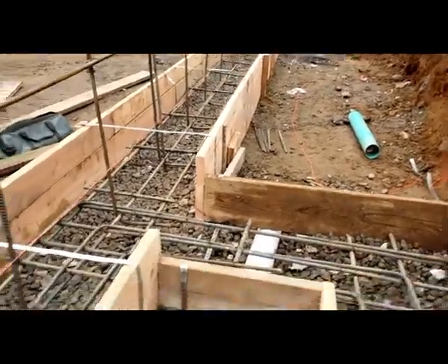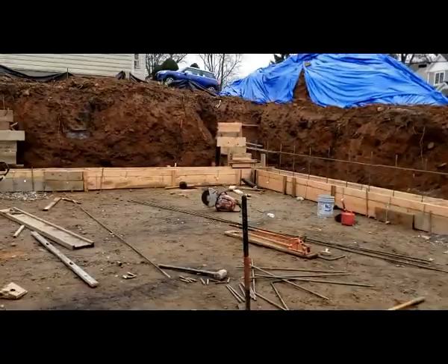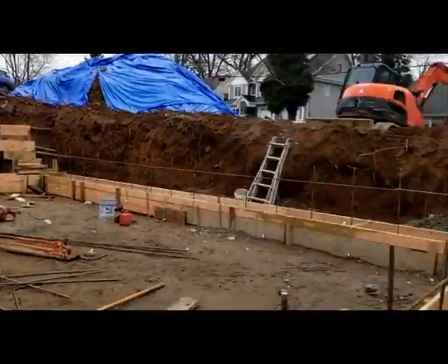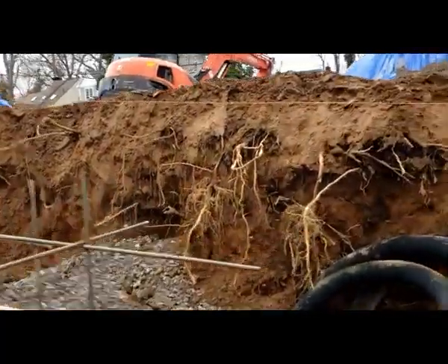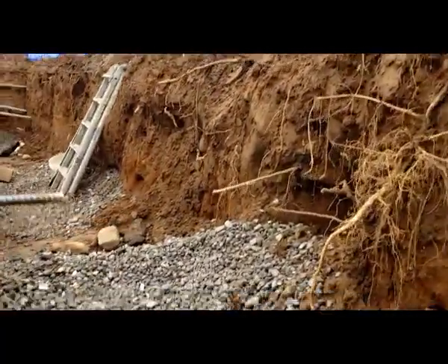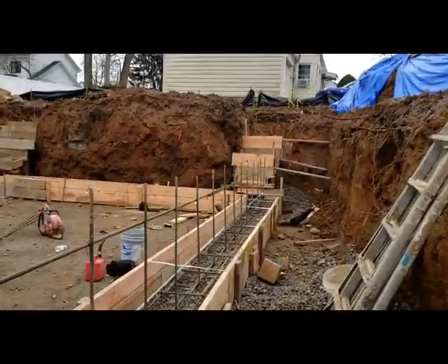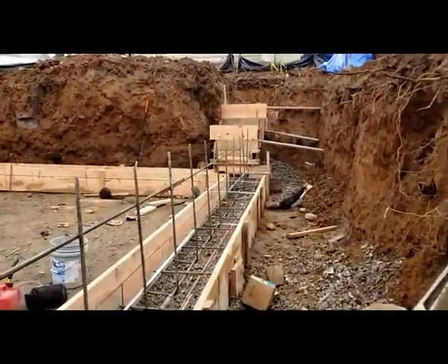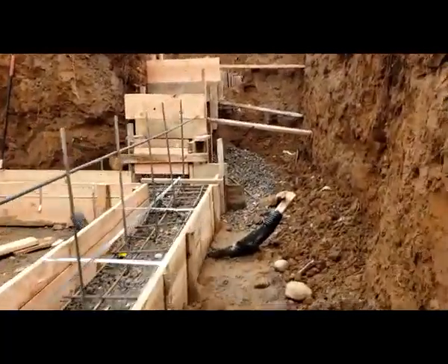Now that moves me to the third important thing. Run all your pipes right now. So I have one pipe here, this is for the drain, and if you see over there, black corrugated pipe, I'm gonna go around. Like you see also, we over excavated. Usually when you do these jobs, you need to over excavate to make sure the guys can walk. Make sure you run your pipes.